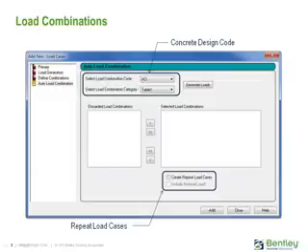You can generate traditional standard load combinations, or you can generate repeat load cases. In a traditional load combination, STAAD.Pro would analyze the model and then algebraically combine the results of each of the load cases in that load combination. If you are planning to perform a P-delta analysis, it's important to generate repeat load cases instead of your traditional load combination. The repeat load option, in contrast, will instruct STAAD.Pro to consider the load cases acting concurrently before the analysis is performed with all of the necessary load factors applied to them.